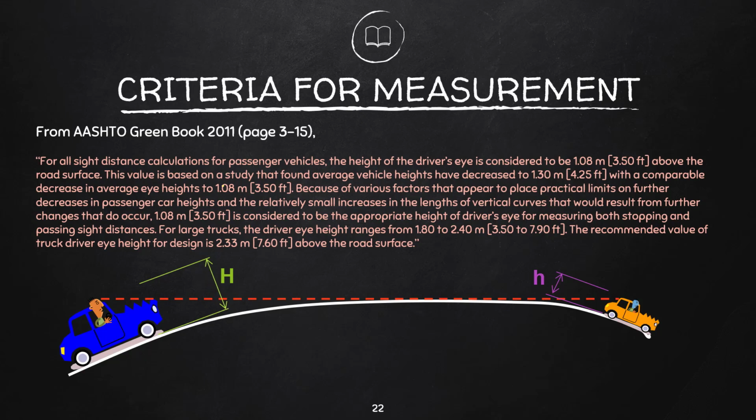This value is based on a study that found the average vehicle heights have increased to 1.3 meters, with a comparable decrease in average eye heights to 1.08.